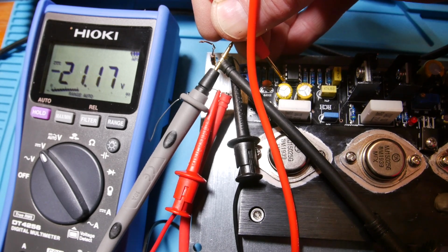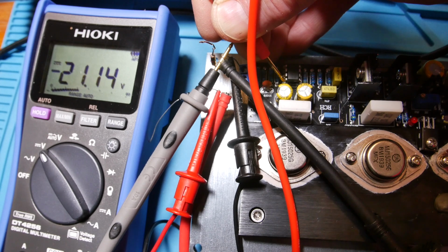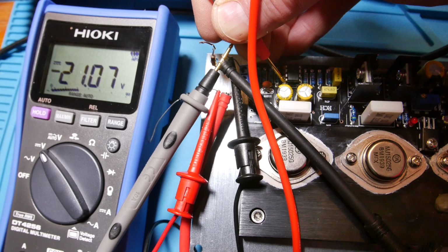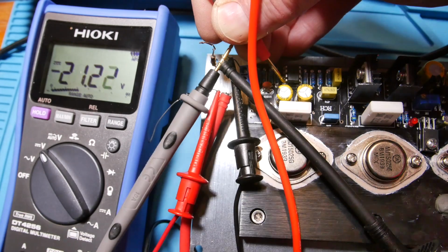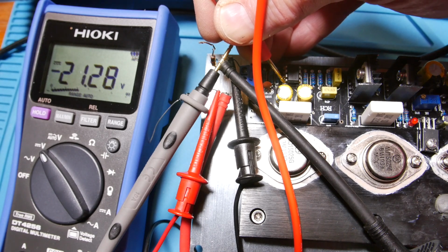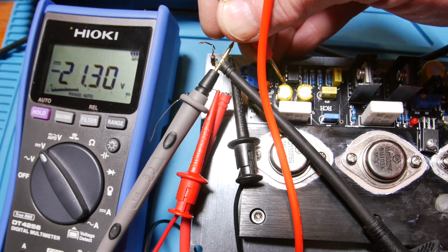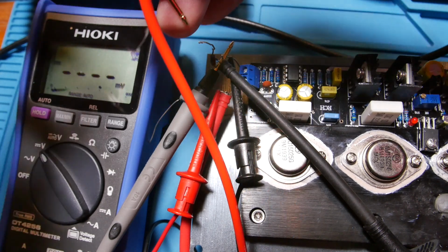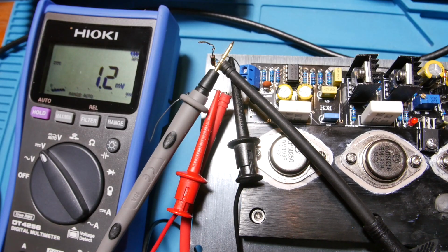And now I'm down at 29 volts right there. And I'm at 28 volts now. So it looks like we do take off just a little bit of voltage off the op amp, dropping the voltage down to 28, but I didn't see the distortion being affected, so I think that's okay.